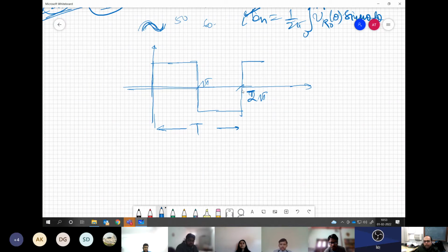So it must be repeating itself over the time period. Then you try to project your sine component over here, let's say the fundamental, on the PWM waveform, and you see that the positives and negatives are kind of matching. So you can expect some non-zero value for this component. You understand my point? Something like odd symmetric, even symmetric, this kind of waveform you have seen. So whatever symmetry this is holding, this waveform also should hold the same symmetry.